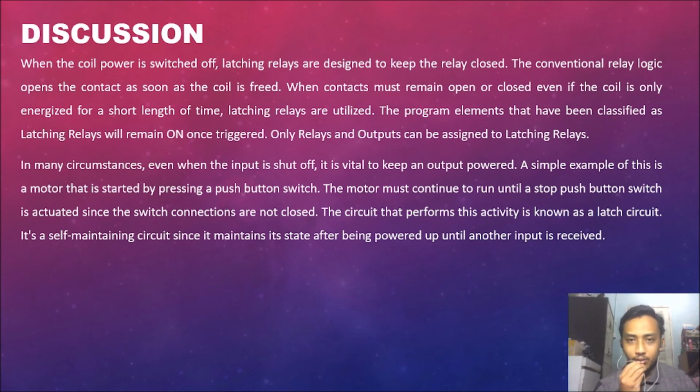When a contact must remain open or closed even if the coil is only energized for a short length of time, latching relays are utilized. The program elements that have been classified as latching relays will remain on once triggered. Only relays and outputs can be assigned to latching relays.